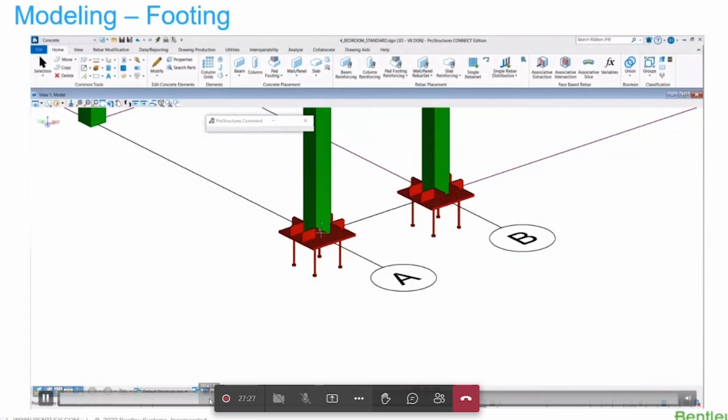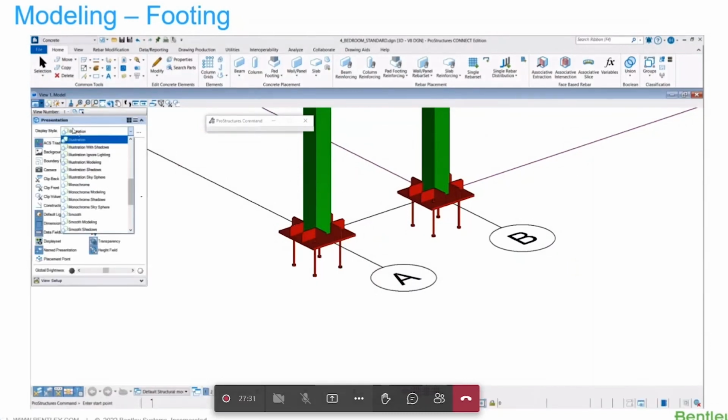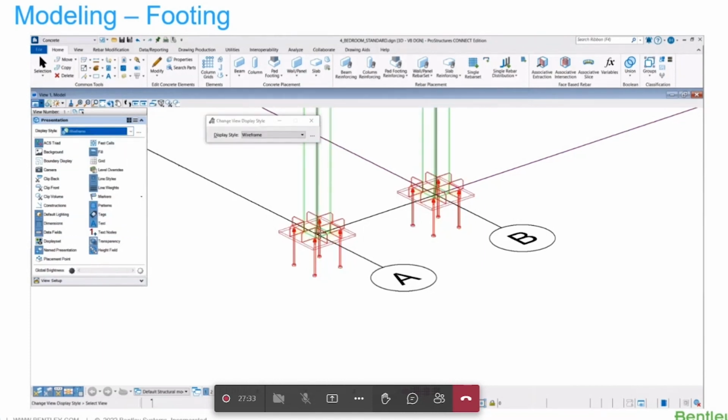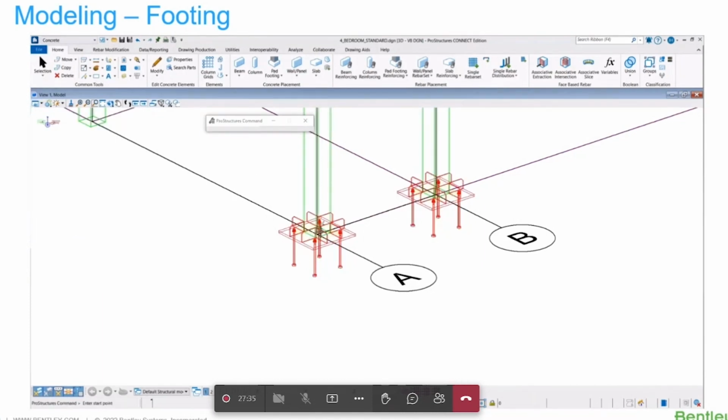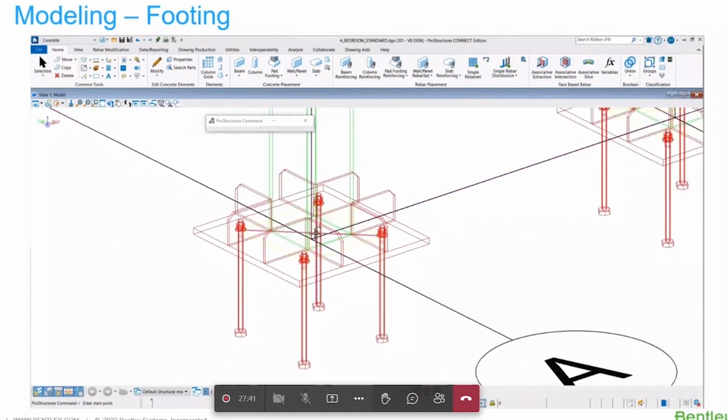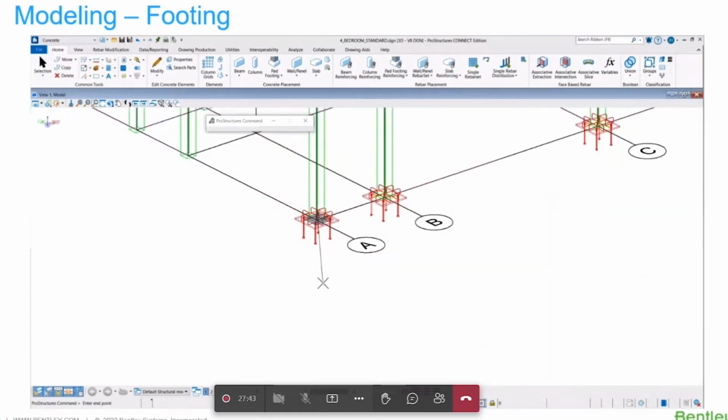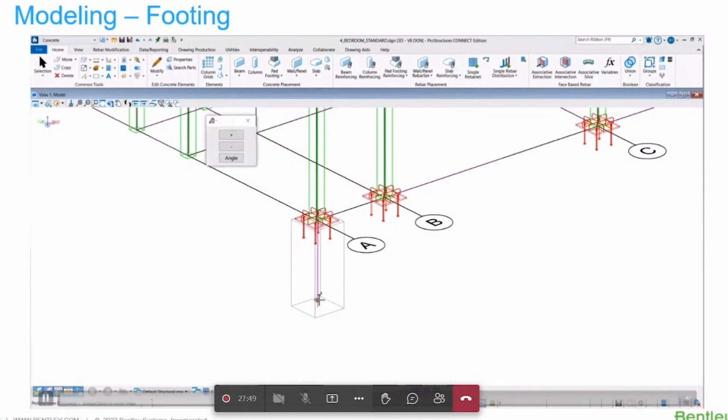And then you can just hover on the intersection of the columns, and then define the orientation where it should be extended. And then now you have a column with the geometry that you already set up.